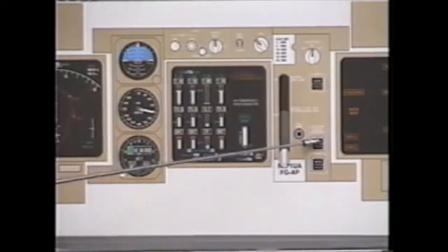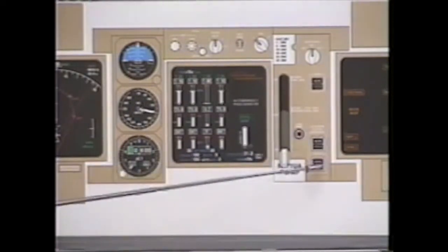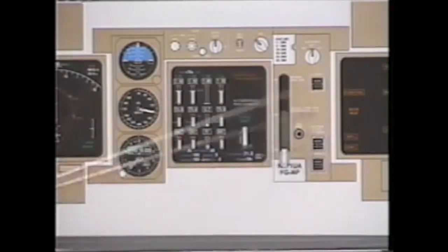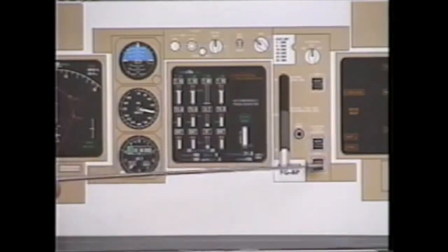These switches simply rotate the up locks for the door and the gear, allowing those 2 items to gravity fall. These switches cannot pull the gear down and locked. The gear must be on the up lock in order for these switches to be of benefit. Also, if you extend the gear through the use of these switches, the landing gear doors will remain open.